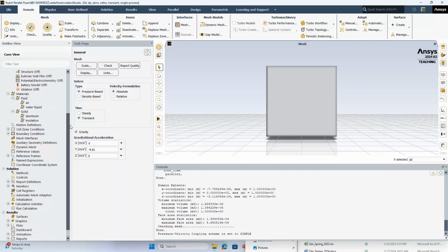Okay, but that is not good enough. The reason, as I have mentioned, why we have natural convection in the air gap and in water is because the densities of the fluids change with temperature, right? So you should allow the density of those fluids to change.